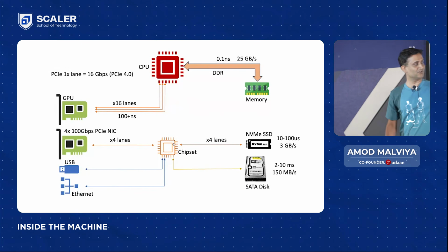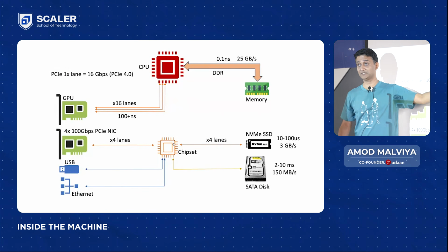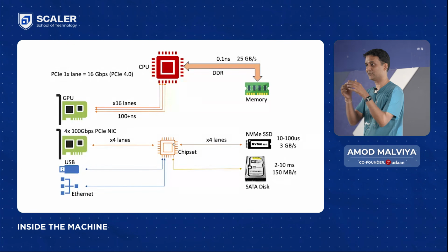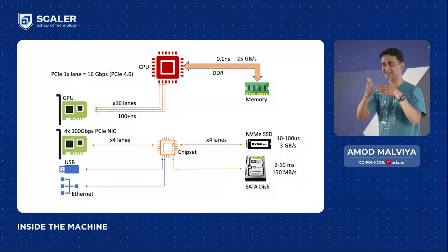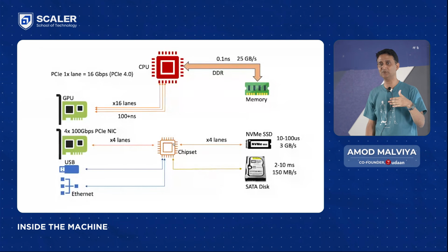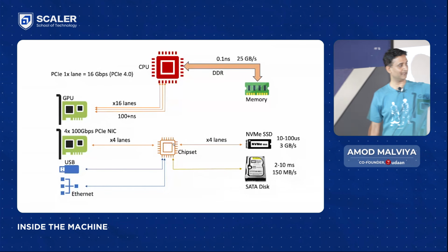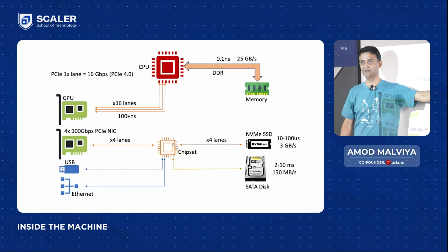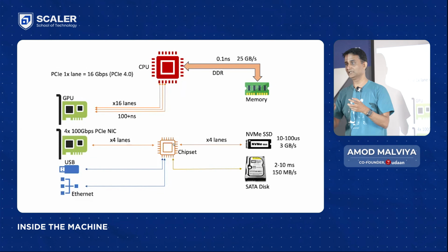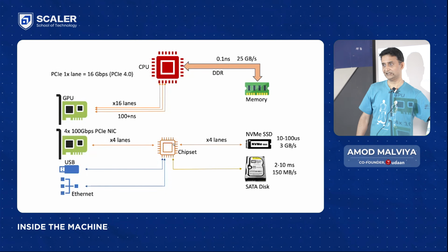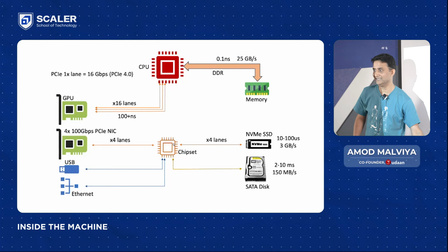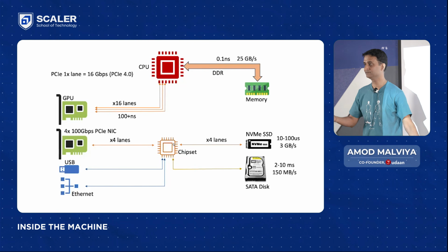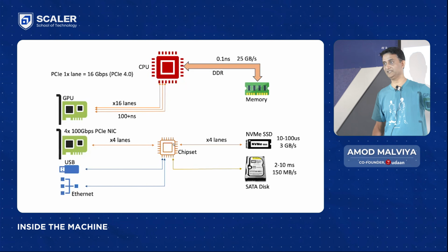Right? So if consumer class CPU has 16 lanes, because remember these are physical links, right? So it's not something that is configurable in software. Physically, those transistors need to be etched into the CPU, right? So the number of lanes are fixed. All depends upon now how we actually make use of it. One of the big reasons why chipset is also used is expanding the total number of lanes that are available. Okay, one is obviously building additional kinds of protocols, and yet another is expanding the total number of lanes.